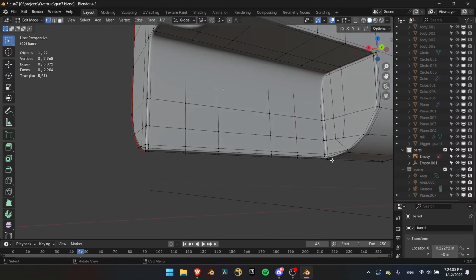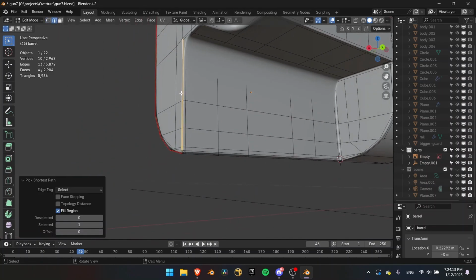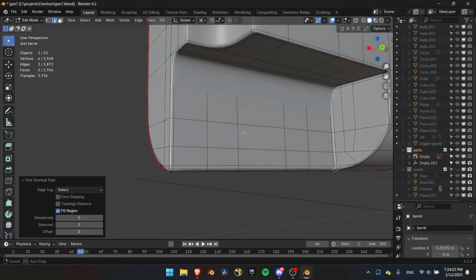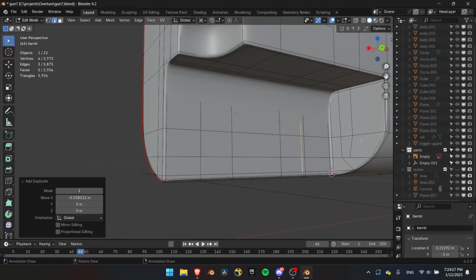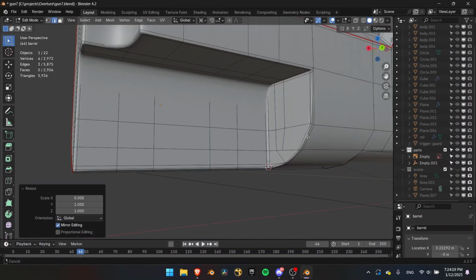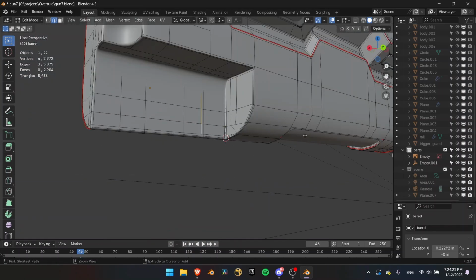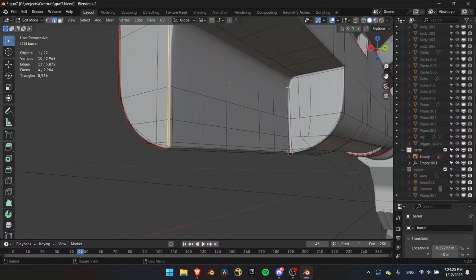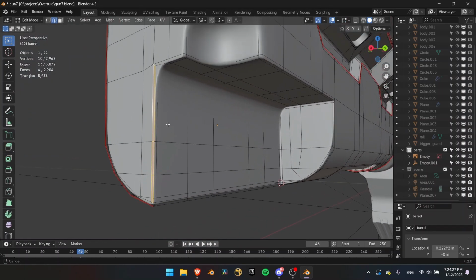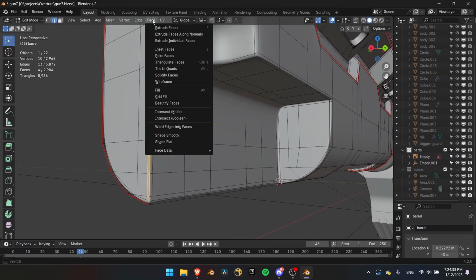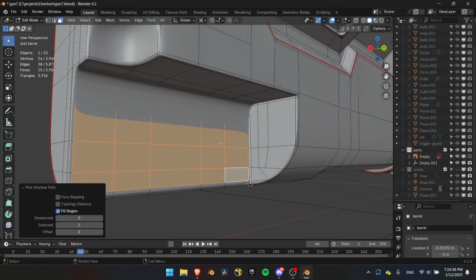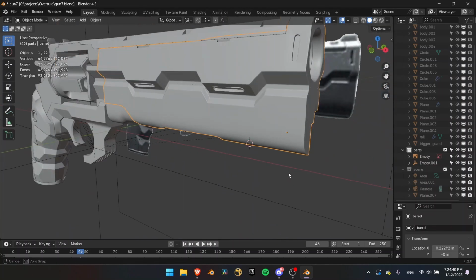You know, I had a point here, put the cursor selected right there. I copied these edges here. Oops. Copy these edges here, and then I just duplicated them over, and then scaled along the x and put to 0, and then it was automatically aligned with this corner. And then I just selected all those, selected all here. And then I used face, and then grid fill, and that automatically created all these faces right here. So that was really useful.